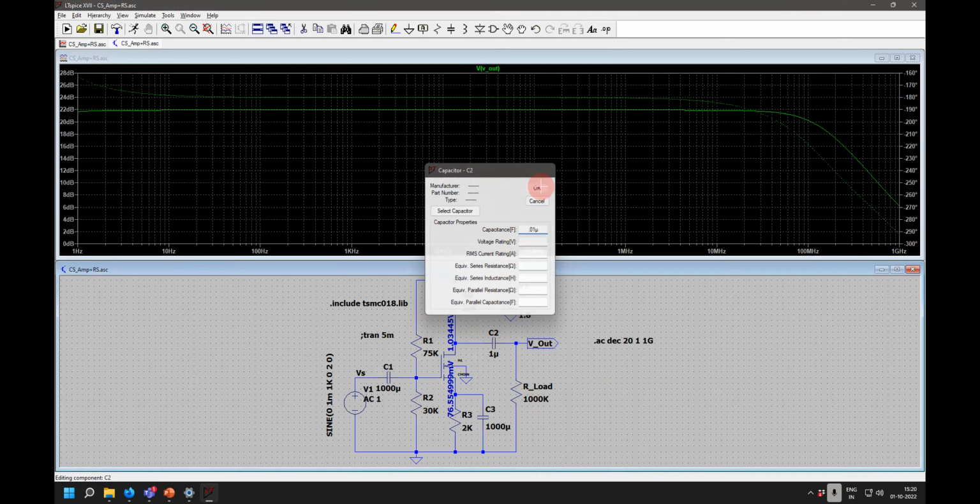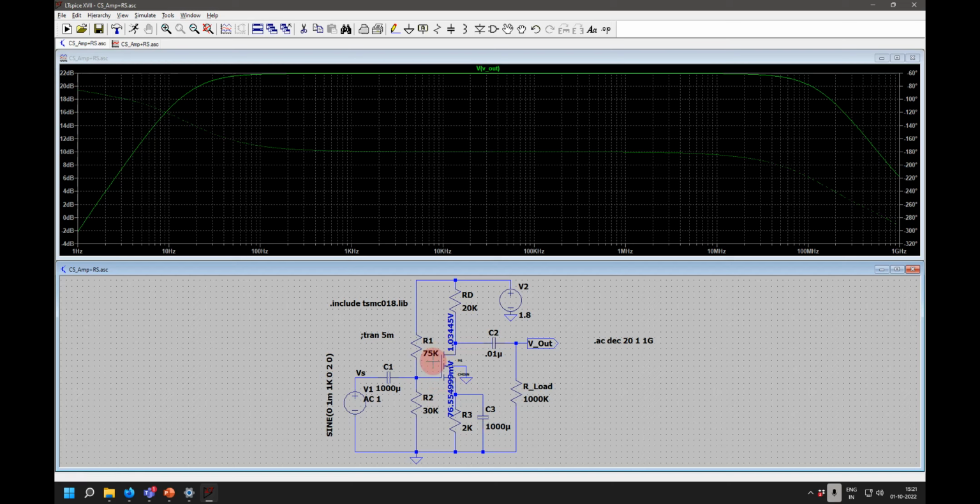At the high frequencies, what is going to have an effect is the parasitic capacitance of this transistor. Now these parasitic capacitances, we can't adjust them; that is not in our hands. They come from the size of these transistors, and the size of those transistors is dependent on the gain and other parameters, as we have seen in the design steps.